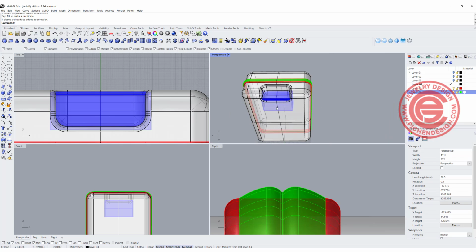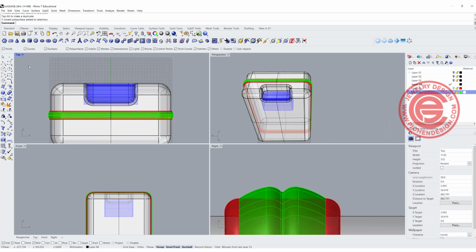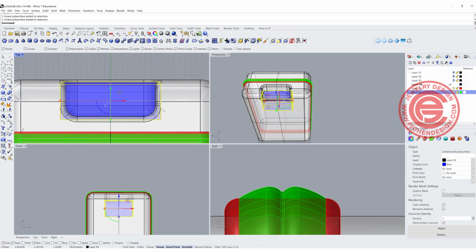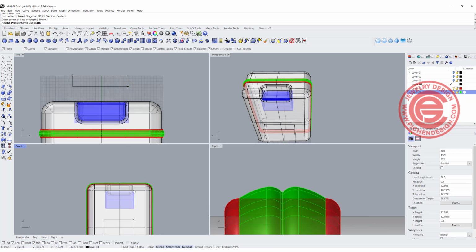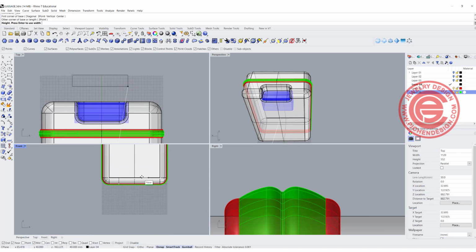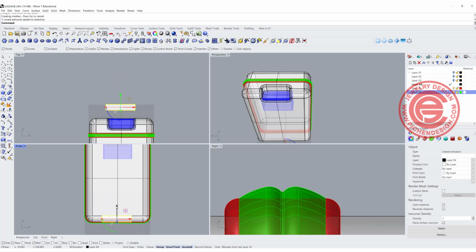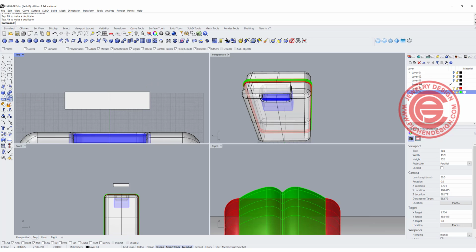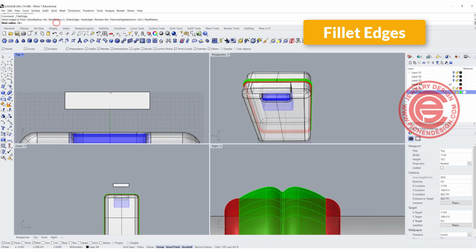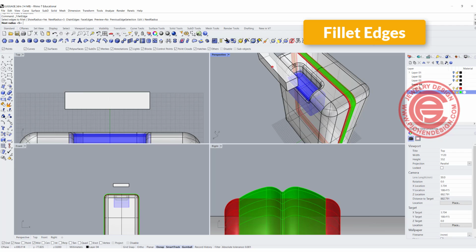All right, so we got something sitting in there. The next one, let's do the handle. Again, I'm going to create something with the arc, because if you have everything just coming out from the primitive shape, and then you want to fillet it, even though you can do something like this. For example, I want the handle to look like this, and let me bring this up here. And you can do the fillet with a different radius. So if you do the fillet like this, let's say I want to go 5 on these edges.